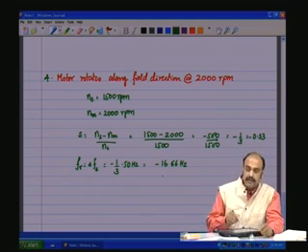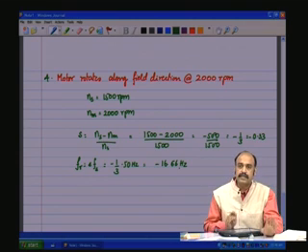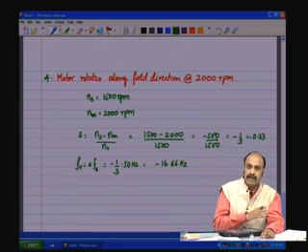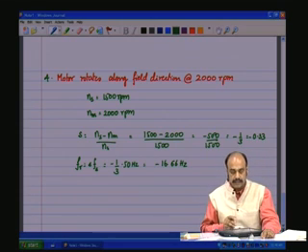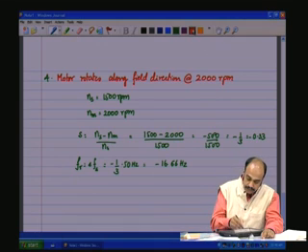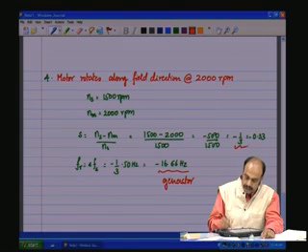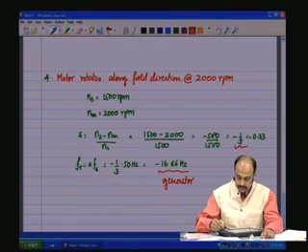When you see the waveform on the scope, it will be just 16.66 Hertz, but the negative sign only indicates that the energy is put back from the mechanical side to the electrical side. So this means that this is acting like a generator because of the negative slip.